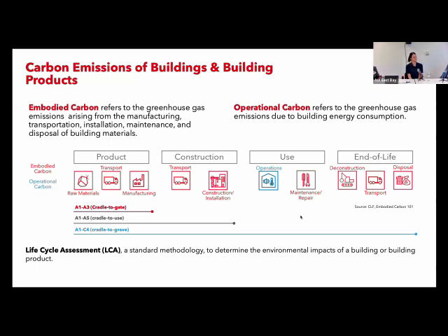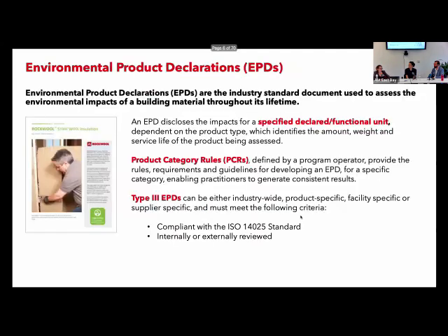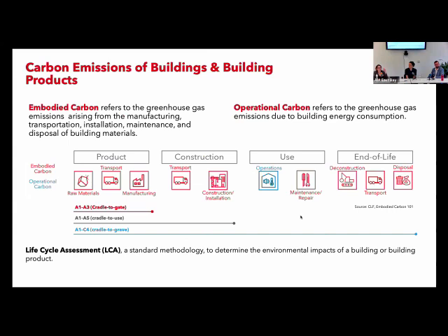Or basically embodied carbon versus operational carbon. What's the percentage? Over the life cycle of the building, operational to embodied is nearly 50-50. There was a question online of what's the balance between embodied and operational. If you look at the life cycle of a building, which typically is judged right now in the United States at 60 years, it's about 50-50.